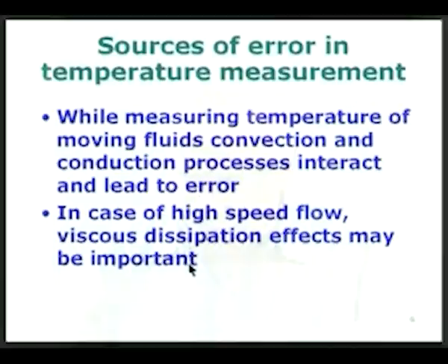The fluid will actually heat up very close to the probe, because the boundary layer is going to be present right next to the probe, and the high speed flow is going to decelerate next to the surface, and because of large velocity gradients which are present near the probe surface, there may be a significant amount of heating. So, in high speed applications, this may be a very important error which has to be taken into account.